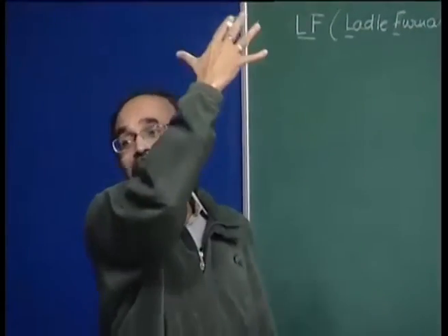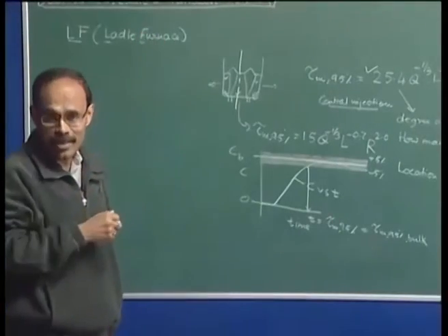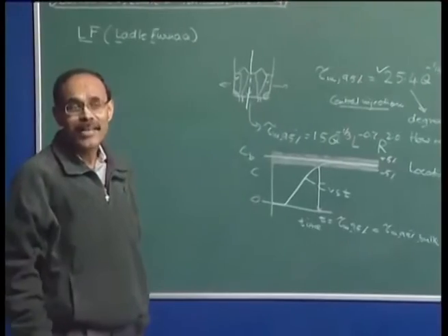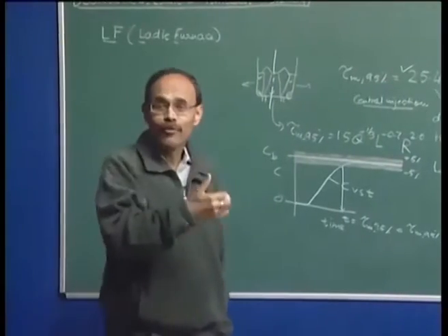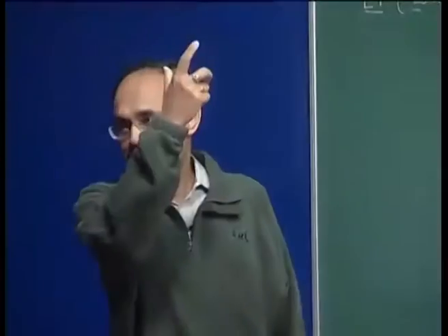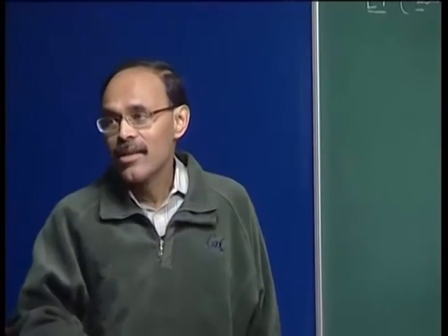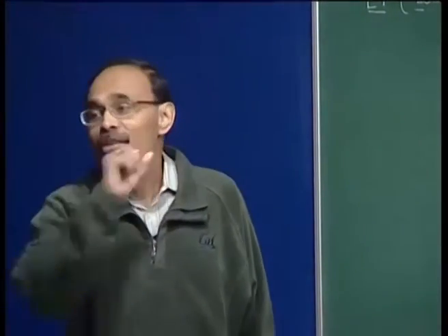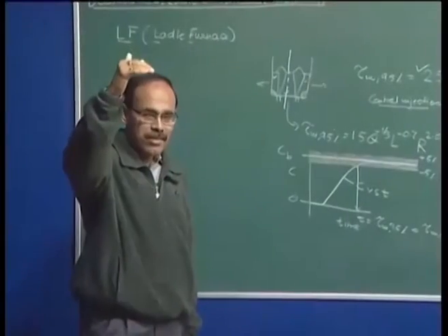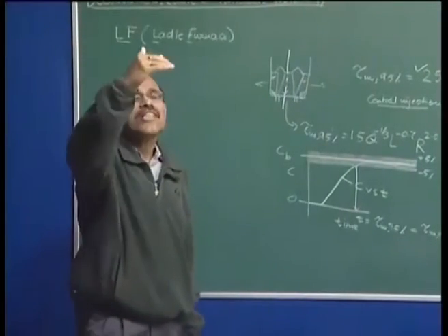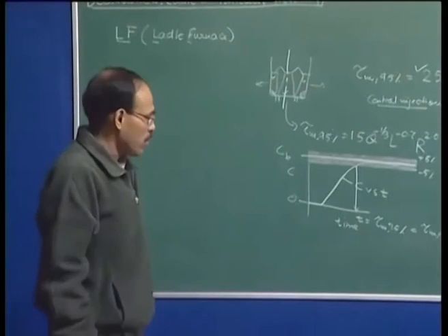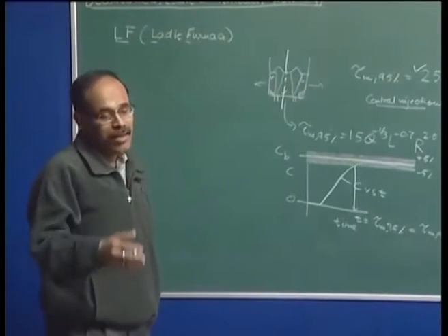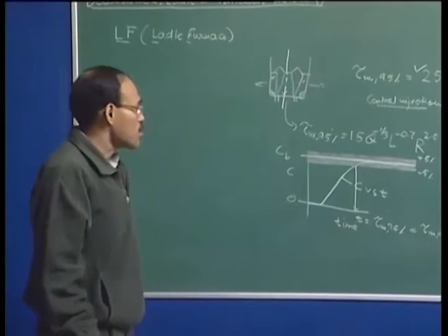It is not desirable that steel from the primary steel making vessel should be tapped at a very high temperature to compensate for this temperature loss or the requirements of secondary steel making. That is a very stupid way of doing things, because the higher the temperature in the primary steel making furnace, the lower the life of the refractories there. So, it is not desirable to increase the temperature of molten steel beyond a certain level in the oxygen steel making furnace, otherwise it is going to impair the efficiency of steel making.